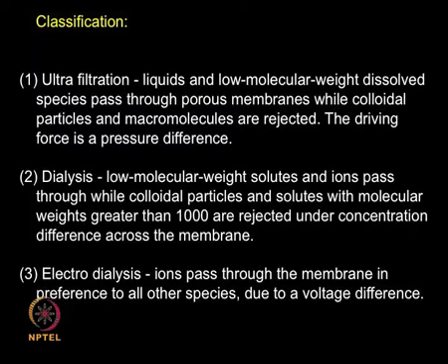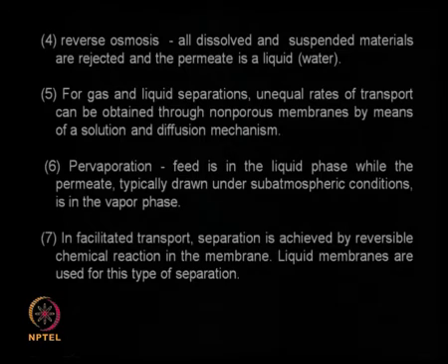Then comes electrodialysis. This happens because of a voltage difference. So you are applying a voltage, so cations will go to the cathode, anions will go to the anode, so that way ions get separated. So here the driving force is the electrical field, whereas in dialysis the driving force is the concentration gradient. Reverse osmosis, this can be used for dissolved and suspended material which will get rejected.